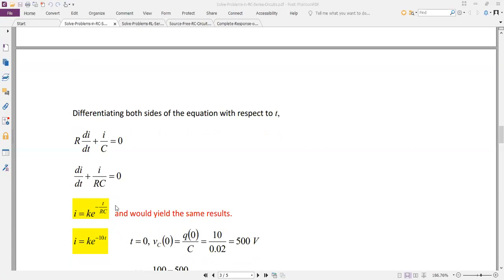How did we get the I? This could be treated as a separable differential equation. Transfer this one on the other side, and the dt also on the other side. The I will be in here. This should give you the equation. You will have an ln of I, which will require you to make the terms in your left side and right side of your equation the exponent of the e. That is why you already have the appearance of the e.